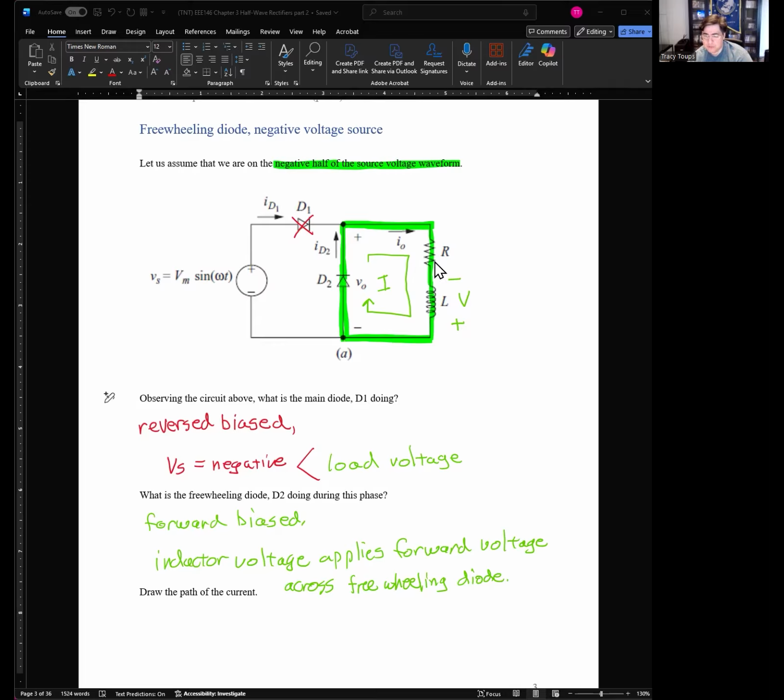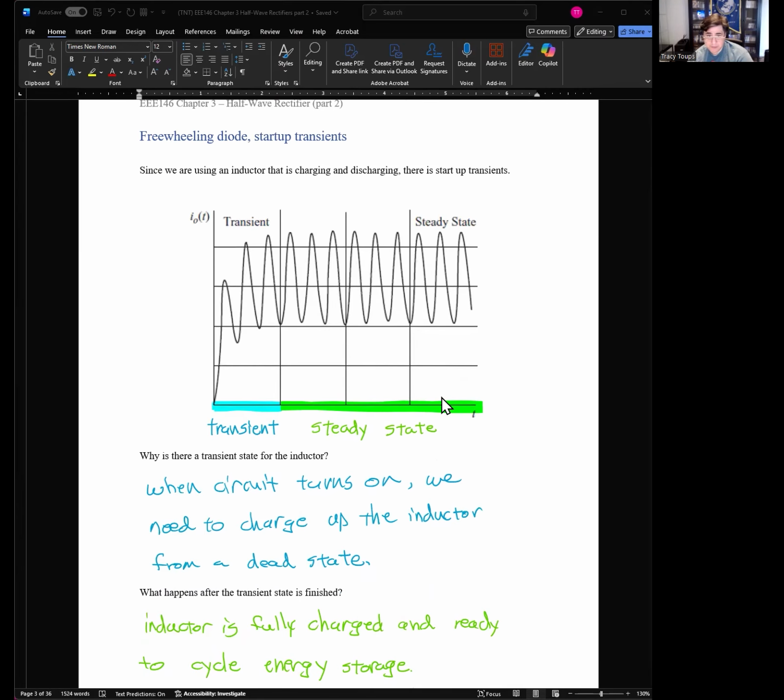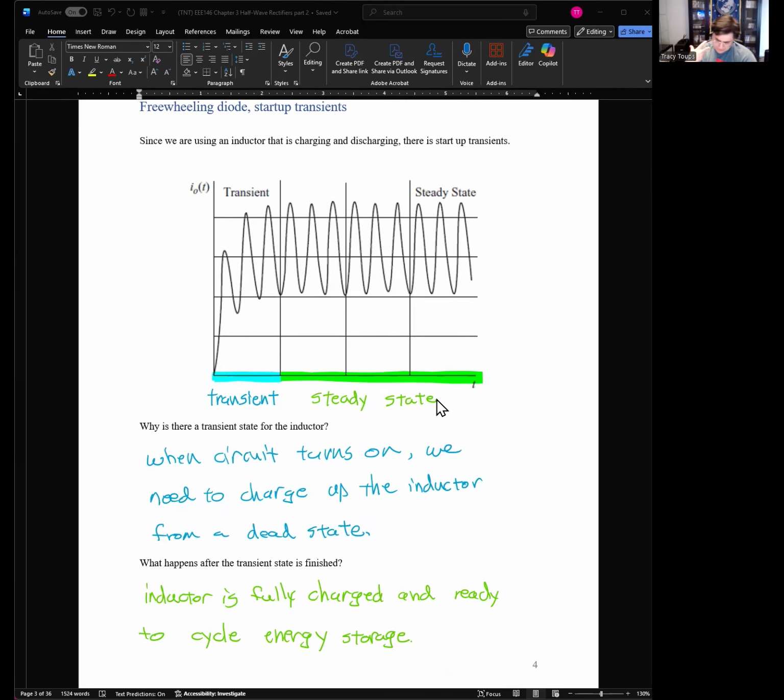So one major loop where the inductor just bleeds its own energy out to the resistor, and eventually this becomes 0 volts. After an inductor bleeds all its energy out, the circuit's inert and nothing's happening. So you have to remember the whole point of the freewheeling diode is just a convenient path for the current to flow.